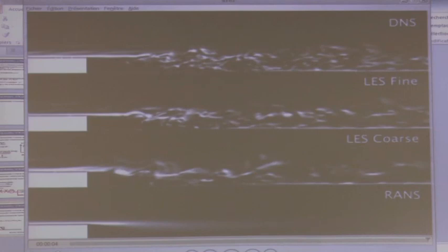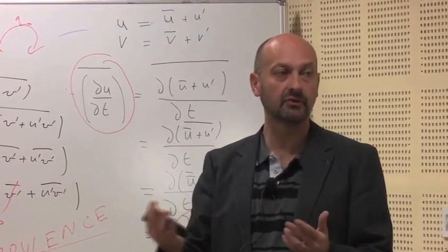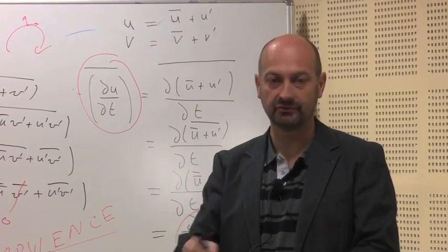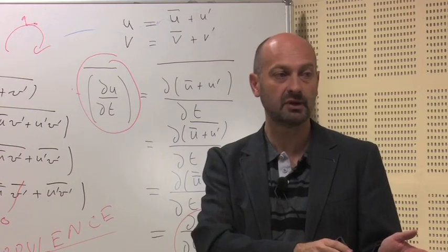So of course, when you have an engineering application, you must validate your CFD with experimental data, and you have to be careful of the errors coming from the two parts. Okay, as I told you, don't think that the experiments are completely valid because there's a leakage, there's a probe that is not calibrated, there's many things, but there's also problems in the CFD.